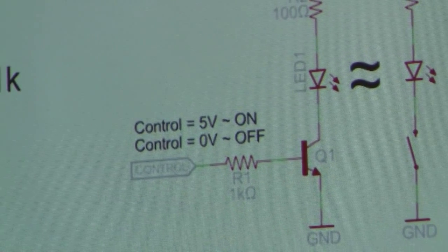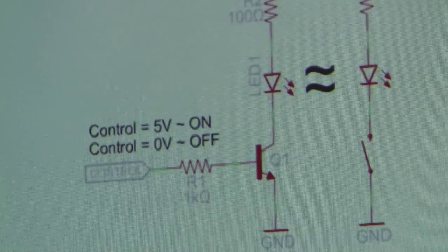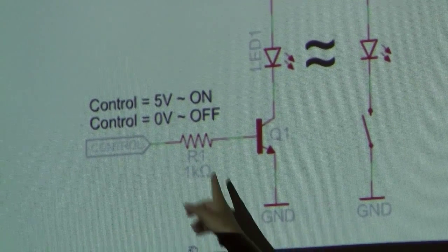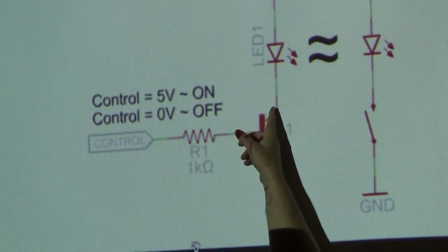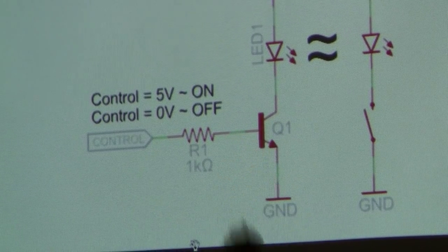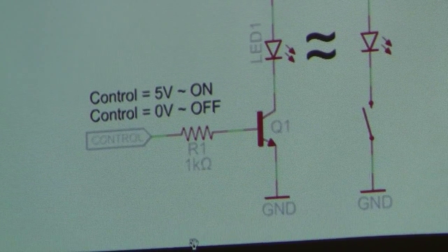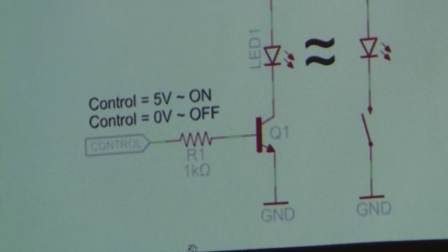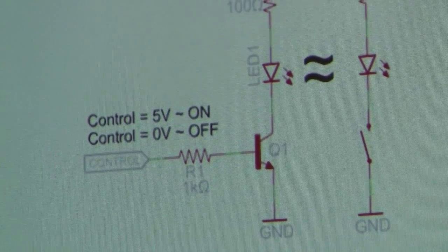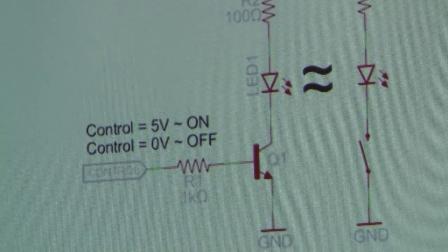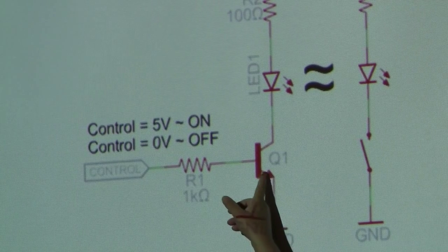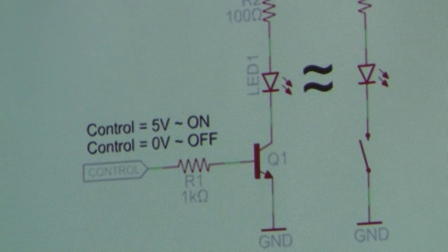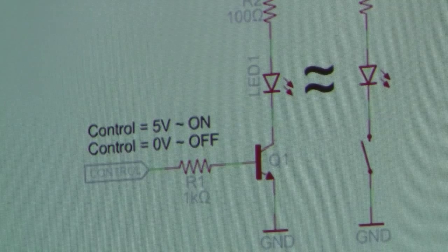Which one of those wires is the base? Oh, the base is the one connected to the base is in the middle, collector on top, emitter on the bottom. The emitter is the one that looks like it's doing something. It's got some parts to it. And the way I remember NPN versus PNP, this is not pointing in. So NPN, not pointing in.